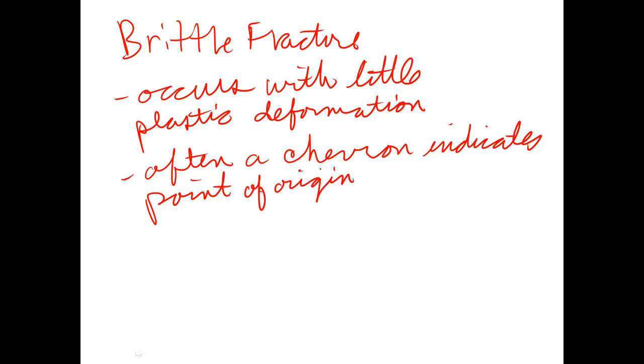And we'll see that the point of origin is typically a stress concentrator of some sort, which probably makes sense given that initial example of the pharmaceutical tablet container, where we deliberately scored the sample and had a stress concentrator to open the package.